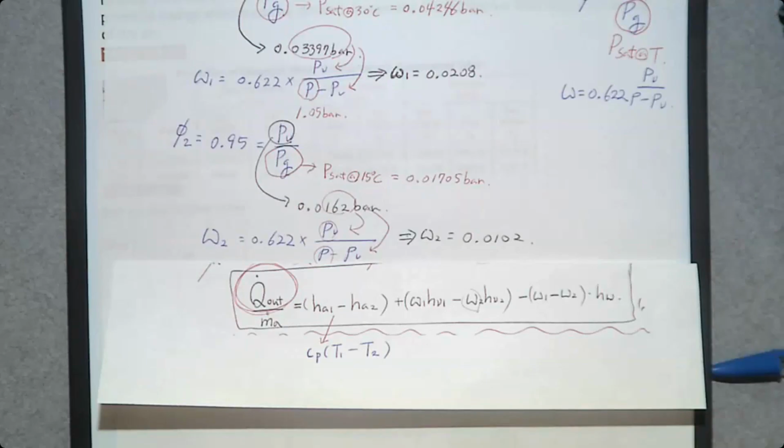So when we talk about pressure, volume, temperature, we don't distinguish air and water vapor for volume and temperature, but pressure is different. What about the mass? Of course, it's different. If the total mass is 1 kilogram, this is going to be mass of dry air plus mass of water vapor.